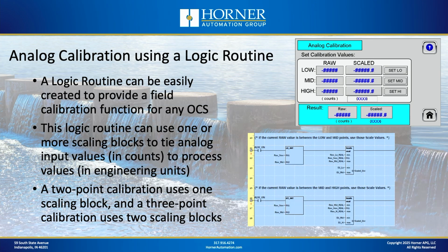Now let's take a look at the method where we use a logic routine to perform our field calibration. This logic routine is not complex. It only involves a few rungs. It also involves creating a screen that a technician can use to walk through the process of doing the field calibration. And it can be used in any OCS, whether that's a Micro OCS, you don't have to use the built-in calibration procedure in the system menu, or any other OCS for that matter.